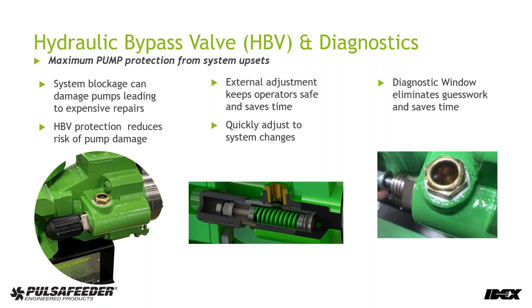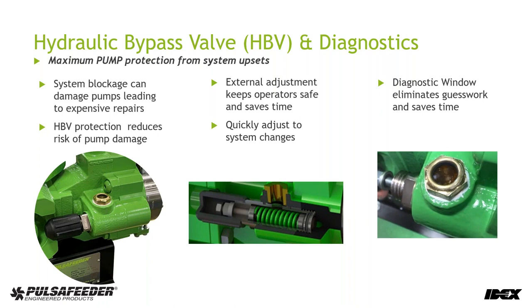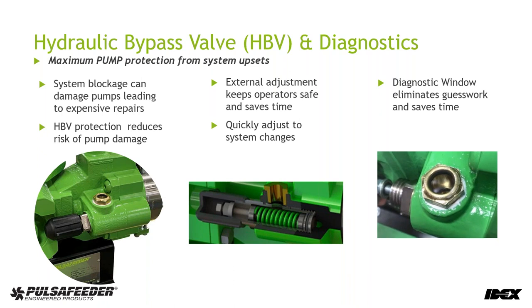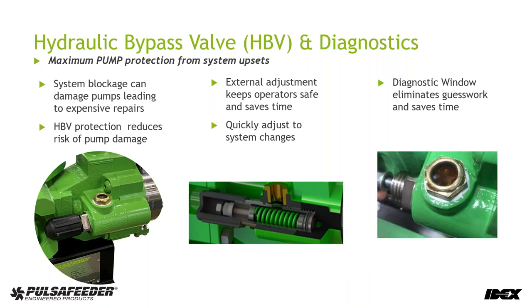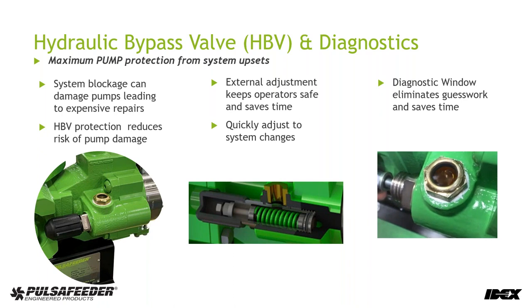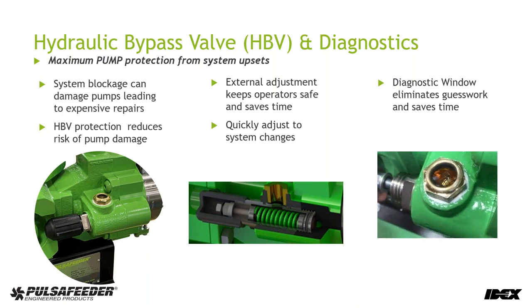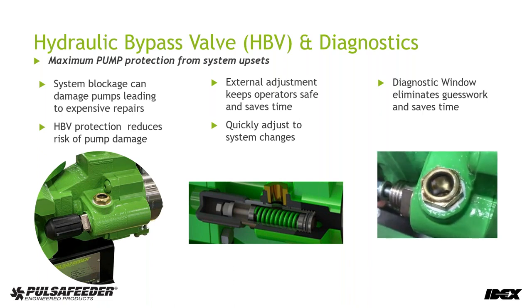So I just really want to emphasize, this protects the pump, and every system should have an external pressure relief valve in its line, so you protect your system. Need to put that out there. But the hydraulic bypass valve protects your pump, and more importantly, your personnel with safety, and gives them further insight into the pump condition. So we don't want any more operators sticking their hands down inside of oily reciprocating pumps to try and adjust them and set them up. That's eliminated with the PulsaPro hydraulic bypass valve and its diagnostic window.